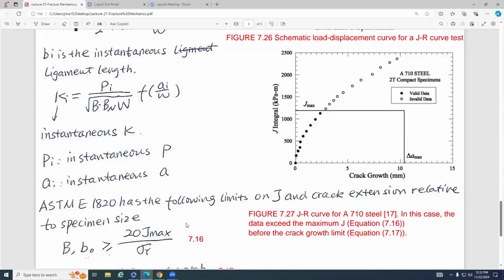Okay, guys, who can tell me what the sigma Y is? The flow stress. Flow stress? Great. And how can we derive this flow stress? There's an equation here. The half of the yield strength plus the UTS. What is the UTS? Sigma UTS.